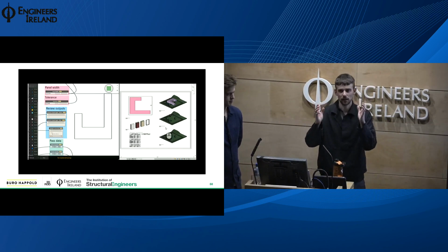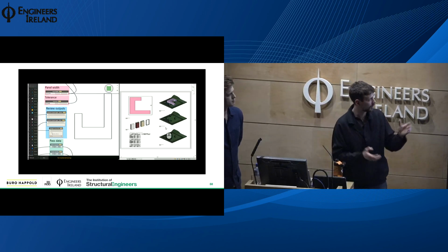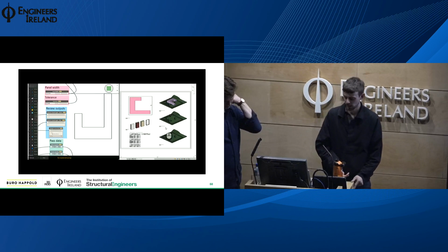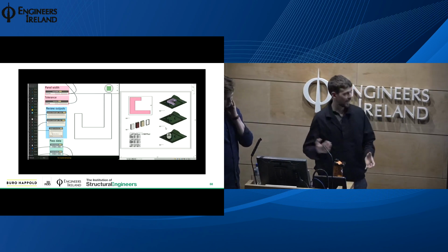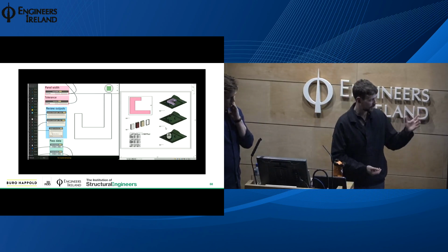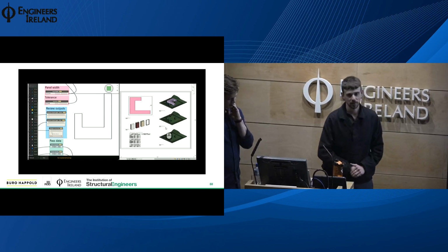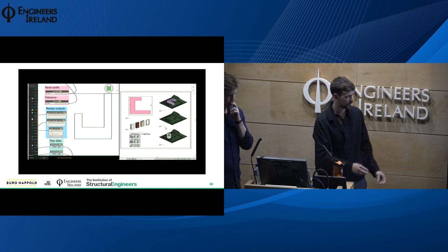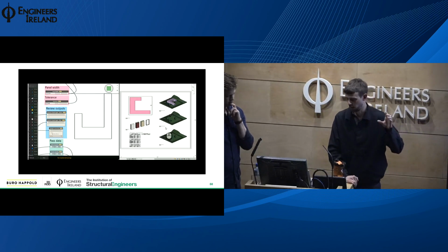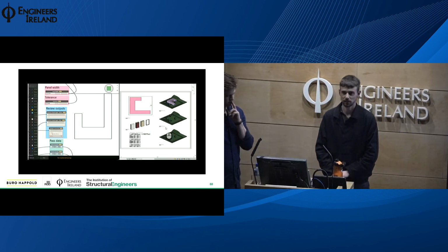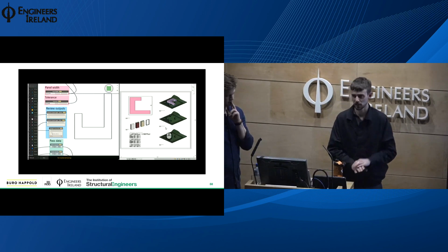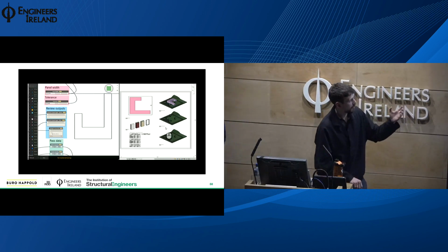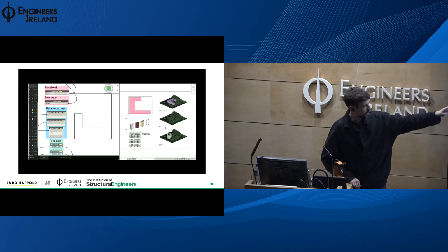You've got those nice regular components of maybe 4 panels of a set size between a column bay, and that means the regularity, the simplicity of design, and the construction abilities of linking with DFMA processes are greatly increased when we have regular construction points. It simplifies the connections, simplifies the details, and really it's about standardizing everything and moving towards this component-based typical design.